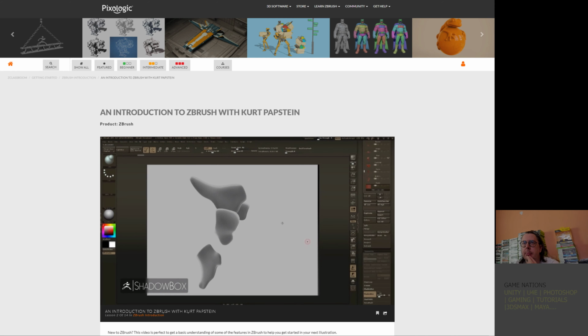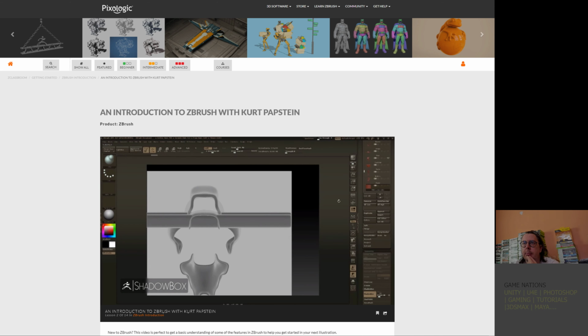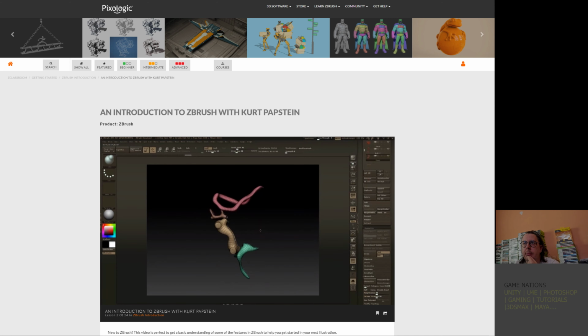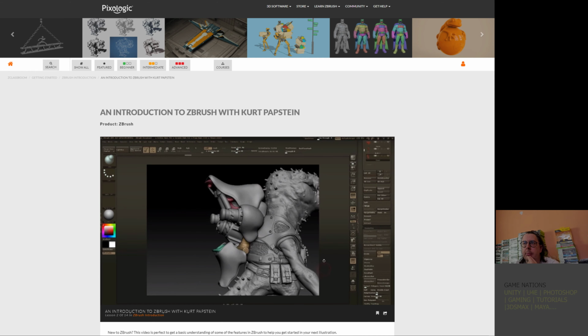Shadowbox is another unique way to build out additional meshes and subtools within your project. You can convert any subtool into a Shadowbox object. Transparency options in ZBrush help you see through any visible subtools, allowing you to paint masks on orthographic planes while still using your sculpt as reference. These masks intersect in 3D space, providing you with a new sculptable mesh in your subtool list. Combined with Dynamesh and clay polish, hard surface elements are rapidly generated without sacrificing any of your creativity.